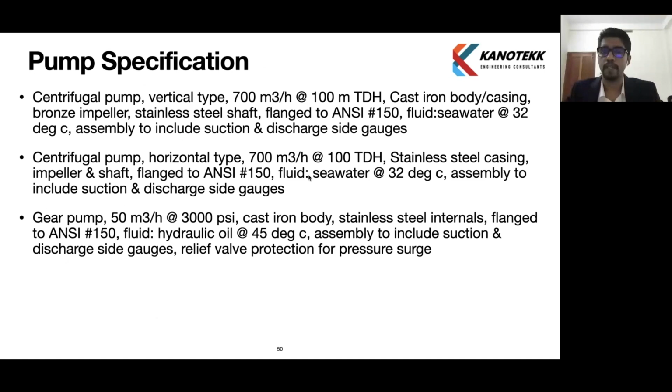to ANSI class 150. So flanges will be rated for ANSI class 150. Fluid we mentioned there, seawater at 32 degrees Celsius. Assembly to include suction and discharge side gauges. So this is the brief description which we give for a pump. We have to give more details like what type of motor is required, electric motor, what type of drive. Similarly, for the motor, what type of enclosure, what type of IP rating. So all these factors have to be mentioned for a pump selection. We only mention here the pump properties. We did not mention the drive properties here.